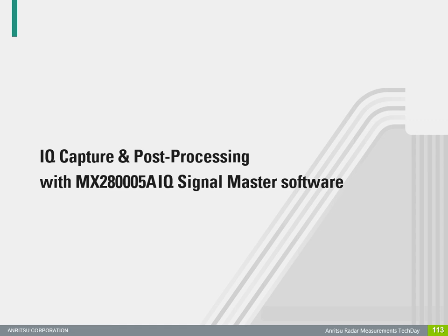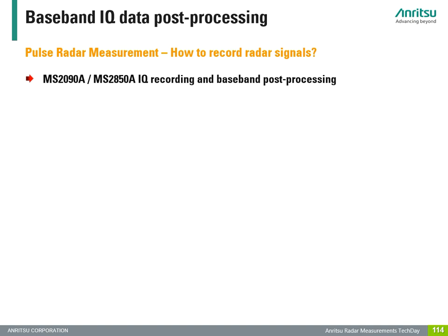IQ capture and post-processing with MX28005A IQ Signal Master. How to record the signal? Recording in this sense means the conversion of a time record length or a continuous time series into baseband data, the so-called I and Q.